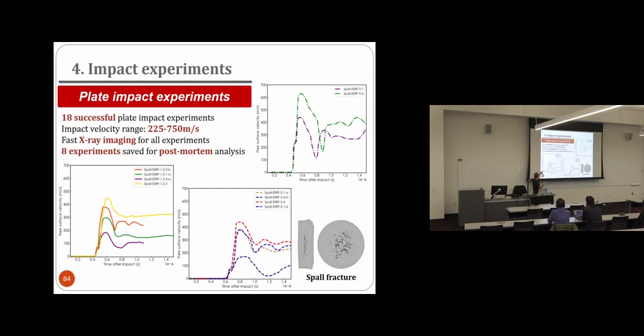So these are samples made of aluminum and titanium, both. We cannot go to higher densities because otherwise there is no transmission, but aluminum and titanium is more or less okay. And these are the signals. You can see that the plateau is much smaller than before because the specimens are smaller. And you can see the duration of the experiment, okay? So again, 1 microsecond. Here, there, there.